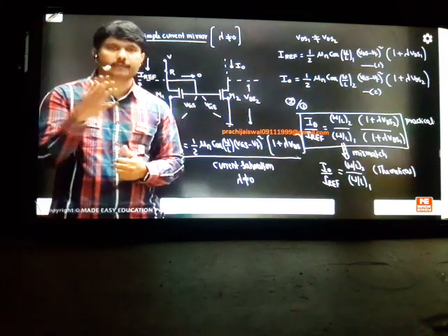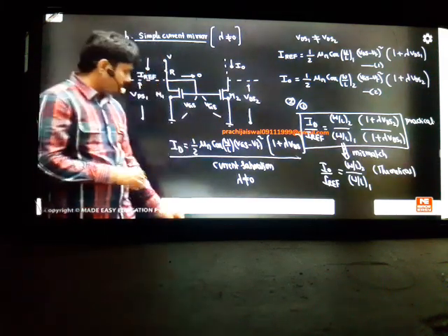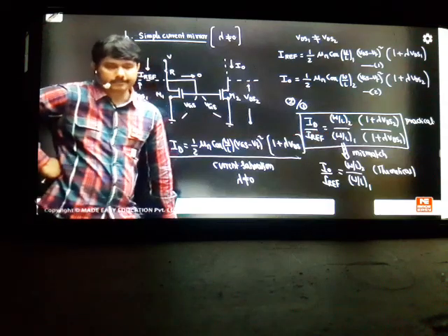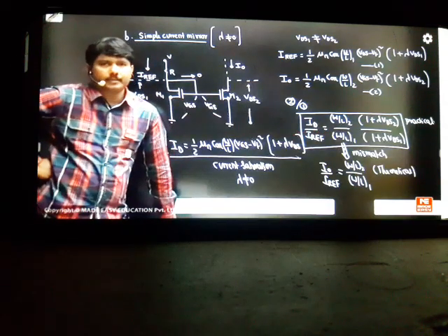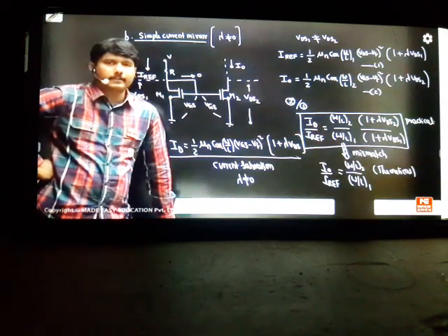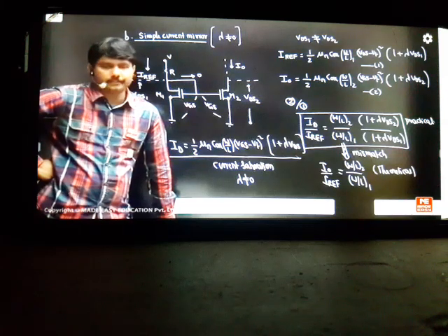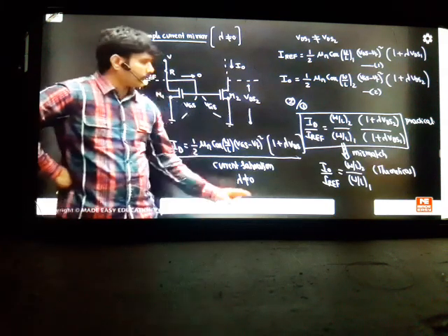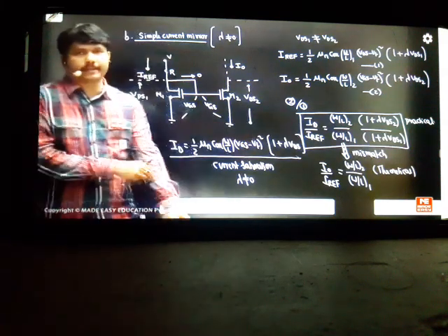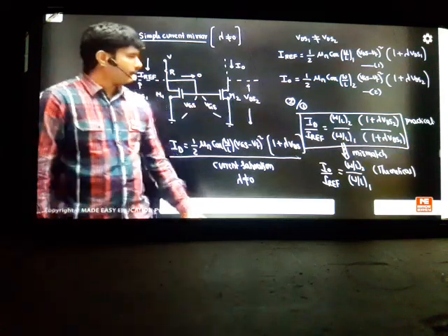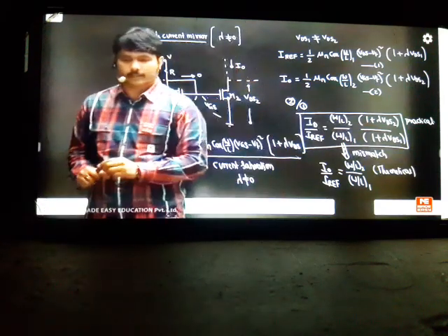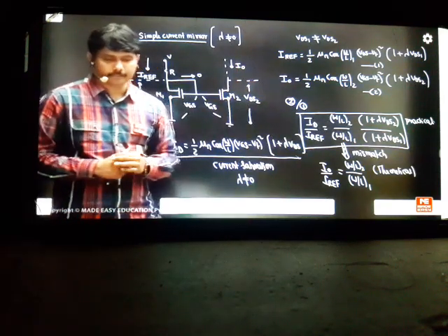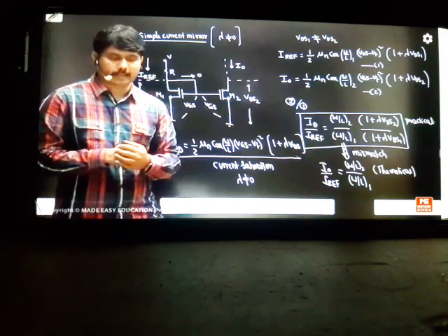How we made VDS1 equal to VDS2 is a story. That is the last topic, and with that we can stop this analysis. So today I think current mirrors are completed nicely. This is the simple way of understanding current mirrors. Only BJT will take more time; MOSFET will be very easy and understandable. So only one topic is remaining, called Wilson technique. Wilson rectified this practical lambda problem. If lambda is given in the exam also, this effect should cancel. How to do that cancellation with a new modified design called Wilson technique, I'll explain. With that we can close the story of the concept called current mirrors.